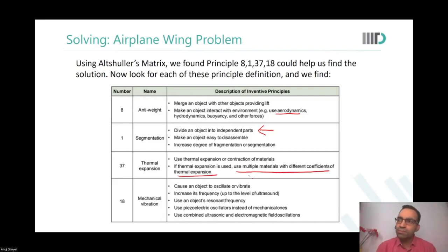In one of the office hours, we talked about bimetals. Remember, where we said two metals are pasted together. Each has a different coefficient of thermal expansion. As the temperature increases, let us say the top metal expands more, the lower one less. What happens? Your material becomes like a curved thing. So you have more surface area inside.